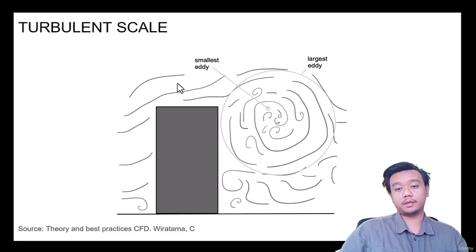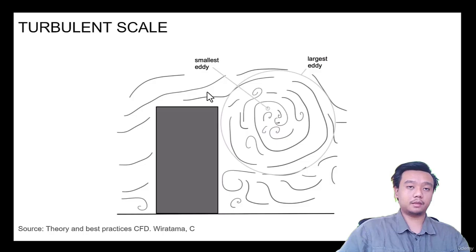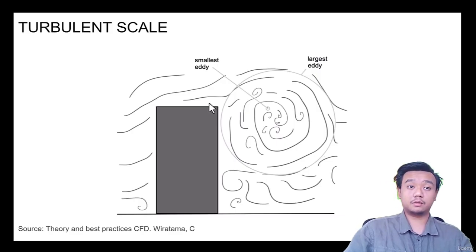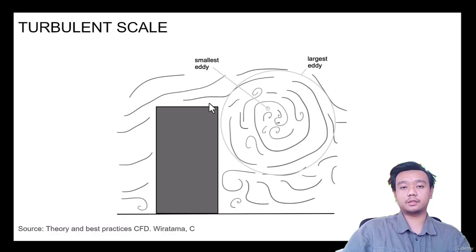which is very hard to handle with computational fluid dynamics. So imagine if you want to fully resolve the turbulent flow, you must make a mesh that is this small, like a couple of millimeters, to cover, let's say, the whole 15 meter building. And also the time step, you have to set it to milliseconds. So the computational effort will be excessively large, and again, that will not be feasible in computational fluid dynamics.